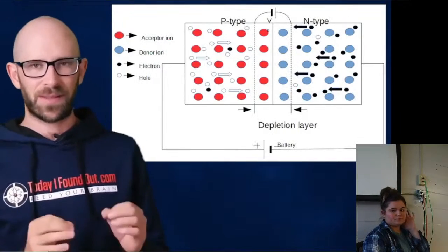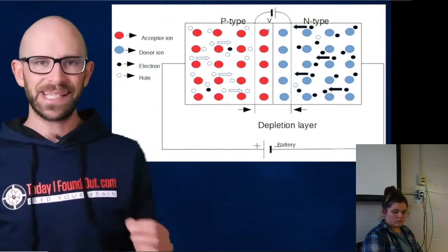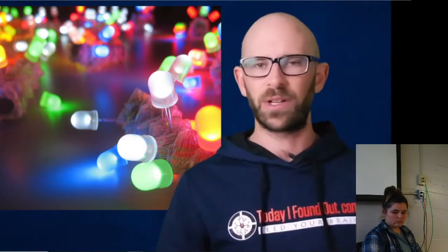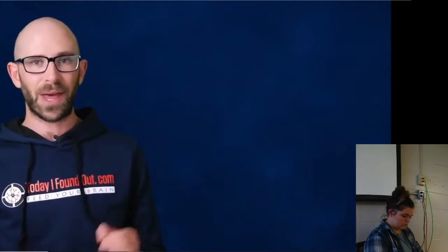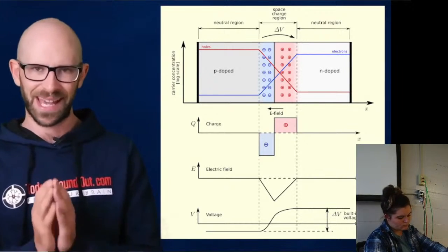It turns out that conventional current will travel from one side to the other, but doesn't like to go in the opposite direction. So you can use this to make sure electricity only flows in the direction you want it to in your circuit, among a lot of other things, because seriously, diodes are crazy useful in a variety of ways. Specialized diodes can do some other interesting things, which I won't go into in this video, but we might address at some point in the future. Generally speaking, these p-n junctions are at the heart of almost all semiconductor electronic devices.